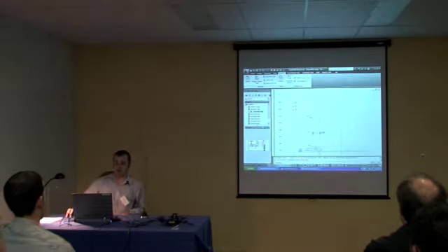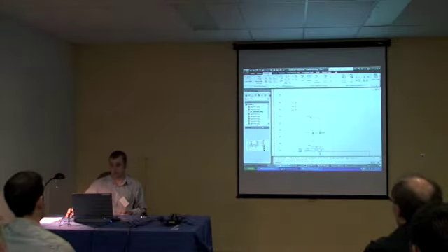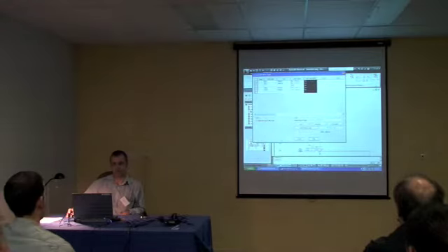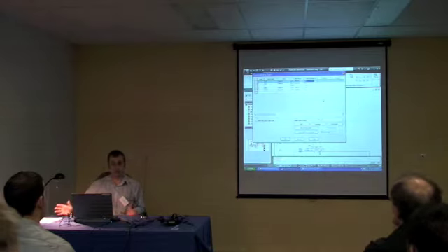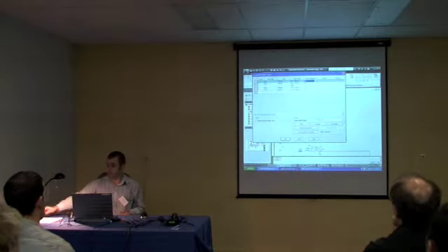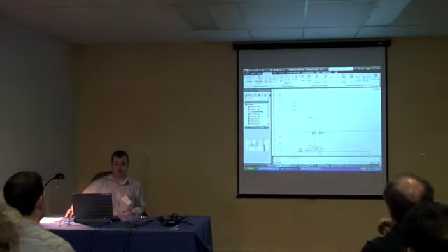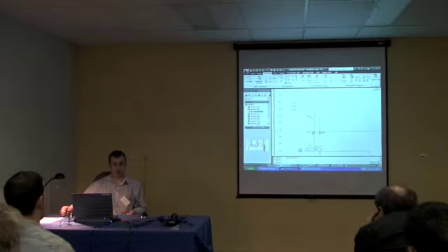Inside of here, you can now tag wire layers as not having wire numbers. So if I go and edit my wire layers, just go here. I now have a wire numbering column here saying, do I want wire numbers on this layer or not? You can turn wire numbers off on certain layers if you require, especially if you're doing block diagrams. So that you can do a block diagram, use the wire function, and not have to worry about the wire numbering.